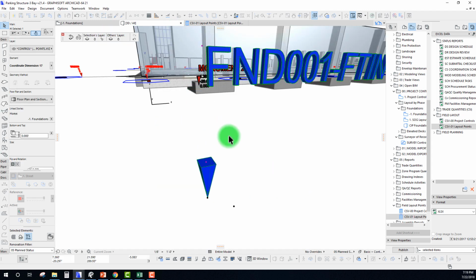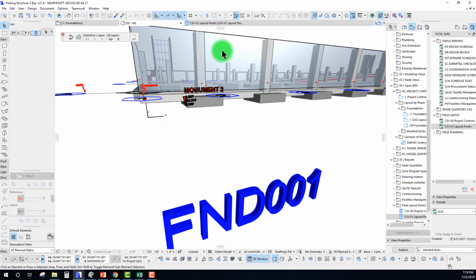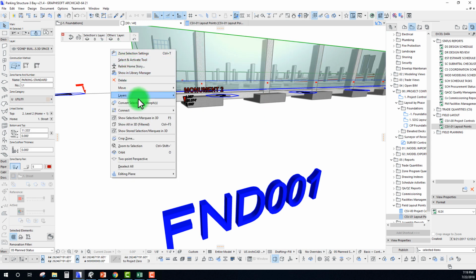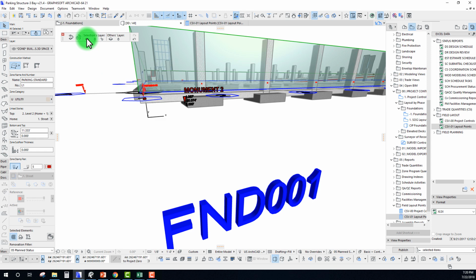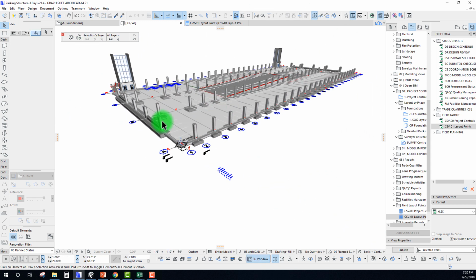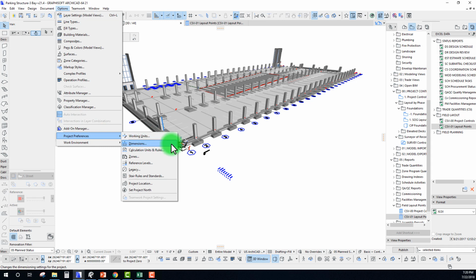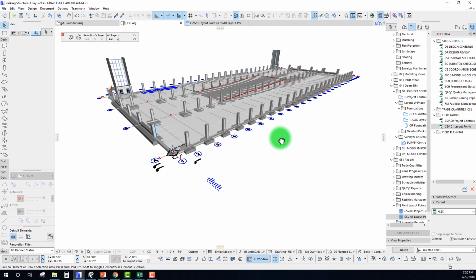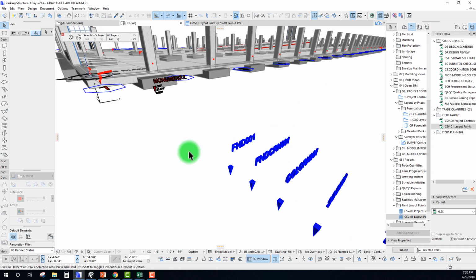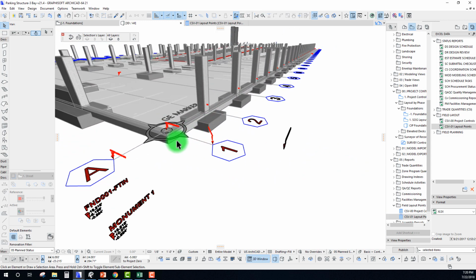And if you do find that you had the wrong settings when you were adding these values in, or when you were creating your points, you can always go back and just grab all of them. You grab every single layout point in your entire project, push it up a foot, push it down a foot, and as long as you're on your right settings here under your project preferences, then it's going to redo all of those.